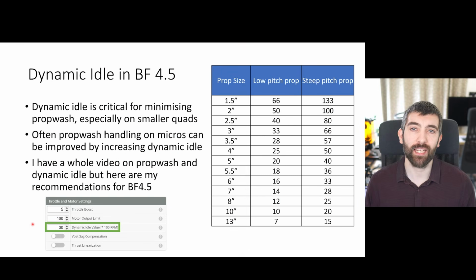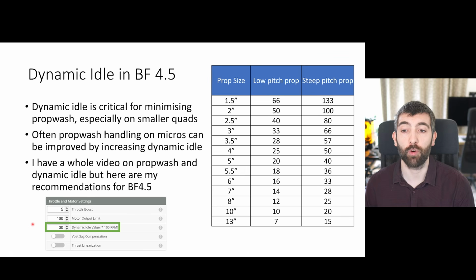Now let's talk about dynamic idle. Dynamic idle is absolutely critical for minimizing prop wash, especially on smaller quads and especially if you're using steeper pitch props. I have a whole video on prop wash, how it occurs and how dynamic idle addresses it, but here are my recommendations for dynamic idle in Betaflight 4.5.